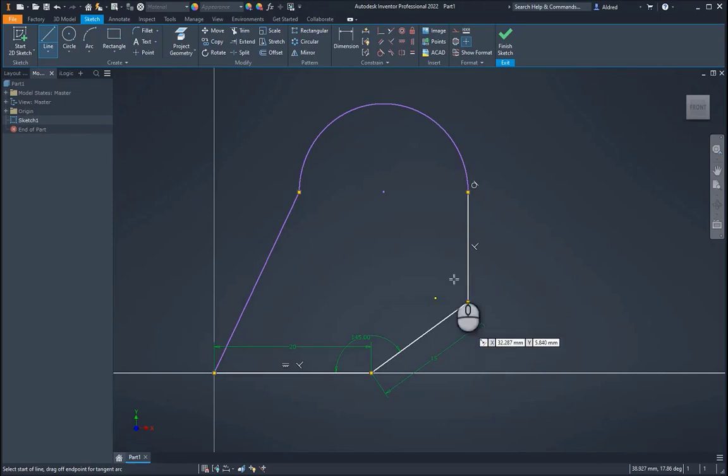Now there are some other things that you can do with the line command as well. The first was, when you held your left mouse button down and dragged it up and left or down and left, it started doing an arc. Now if I just hold my cursor on this arc and hold down my left mouse button and drag out, you'll see it actually draws a line perpendicular to that arc. Cool. Okay, press escape to get rid of that.